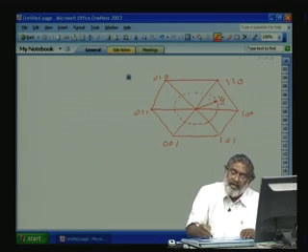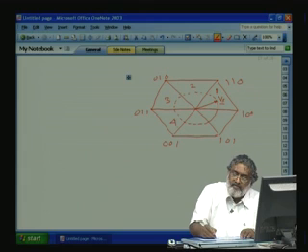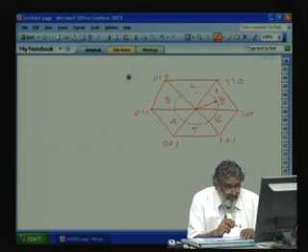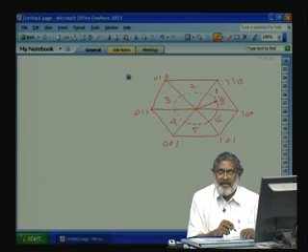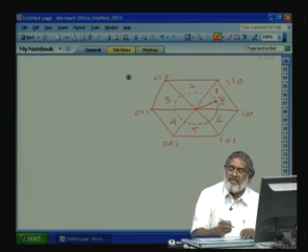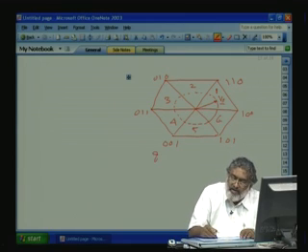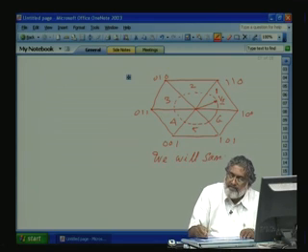If you see here in this hexagonal space, there are 6 sectors, sector 1, sector 2, sector 3, sector 4, sector 5, sector 6. In these sectors, suppose Vs, the reference phase voltage, is in sector 1, and our reference space vector is rotating with uniform speed. So, what we will do, we will sample this rotating reference space vector.